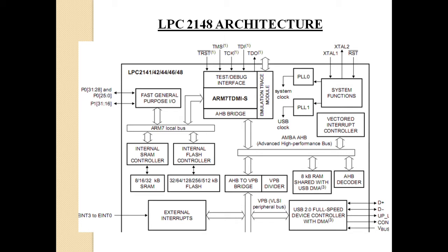Where will you store the program? Here the program is ADD, or where will you store the instruction? The program will be stored in a separate memory known as flash. So in this LPC2148, you have certain KBs of flash and certain KBs of SRAM depending upon the serial number. In 2148, you will have this much flash and this much RAM. This architecture block diagram is the same for 2141, 42, 44, 46 and 48. Only there is a variation in the RAM size and flash size.